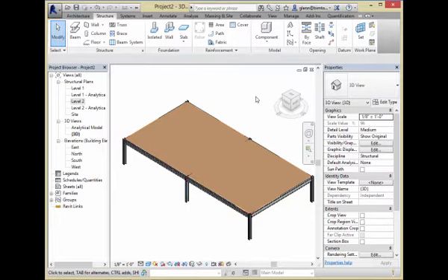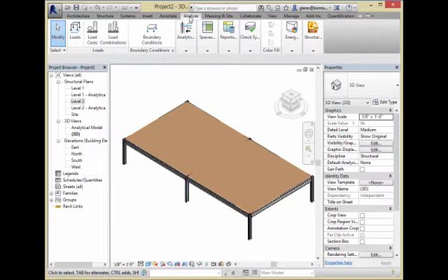One thing that we need to do for analysis is we need to put something on called boundary conditions, where we say, hey, where are those hard parts where the Earth is going to resist and we cannot go any further? Because we need to have a reaction somewhere. So on the analysis side, we go through and put in a boundary condition. All the analysis stuff lives under this area over here called the Analyze tab, and there are boundary conditions here.